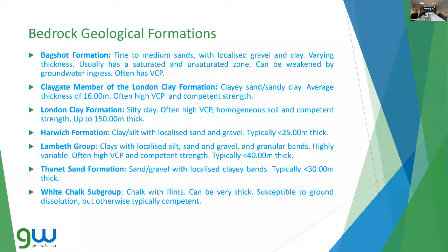The bedrock geological formations, I will briefly go through those as well. We have the Bagshot Formation, localized, sometimes in North London, close to Camden. That could be granular. It often has volume change potential. We do have the Claygate Member and the London Clay Formation. Sometimes you get the Harwich Formation locally, and then at the outskirts you have the exposure of the Lambeth Group.